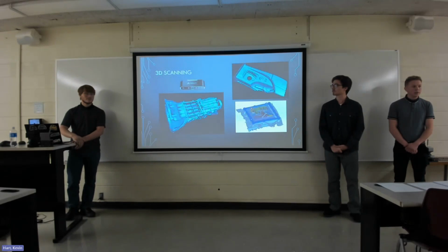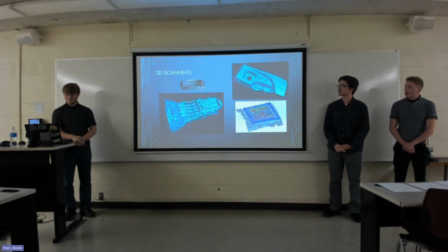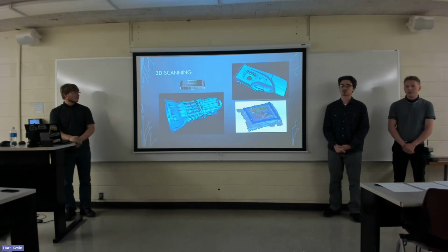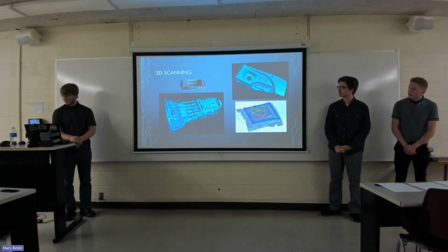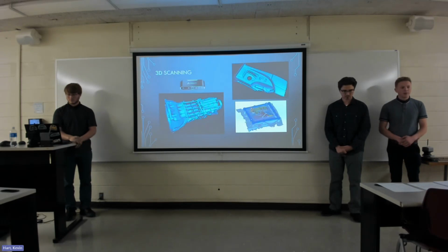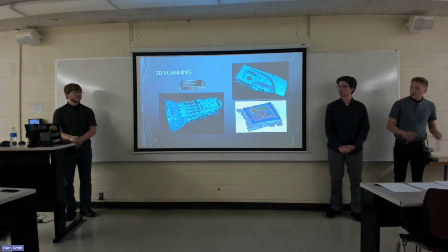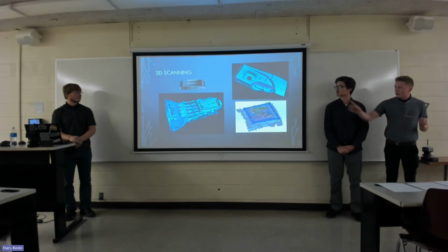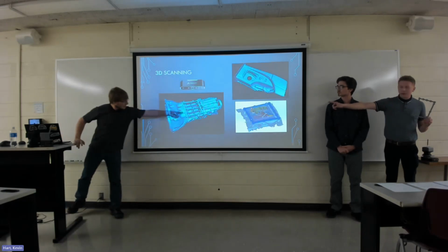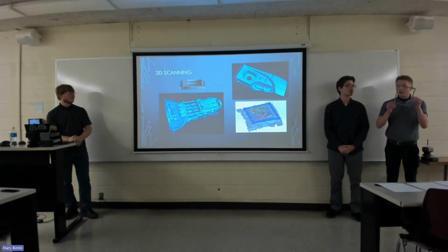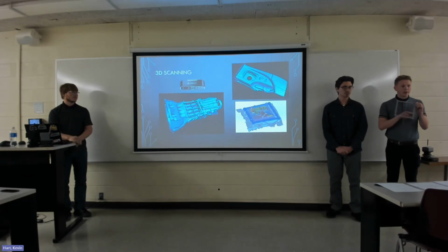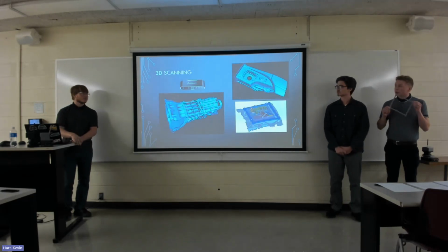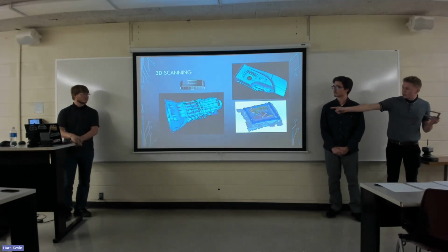The next thing we did to research this project was to use a handheld 3D scanner to fully get all the geometry of the SMG3 transmission, as well as the interior console and trim, to see what geometry we were limited in. So using the scan, we were able to zoom in on the shift selector portion where the electrohydraulic unit mounts. We were able to pull the bolt pattern off of the transmission using the 3D scan. And using this, we were able to determine the maximum area that we could use to design our transmission interface to fit within, as shown in that figure there.